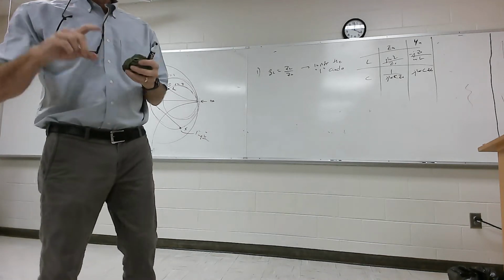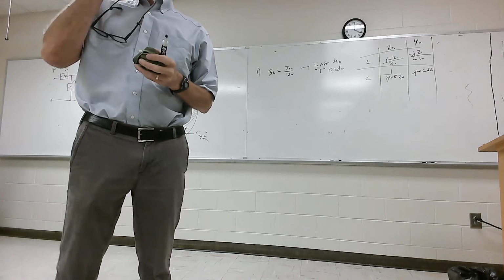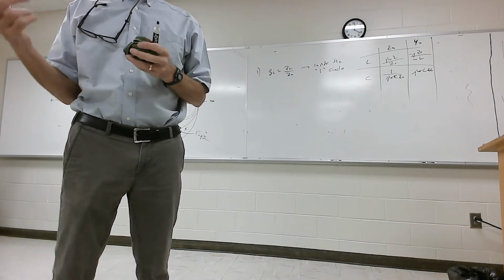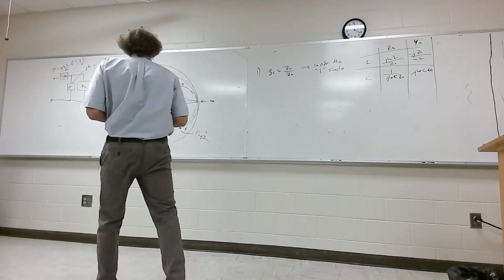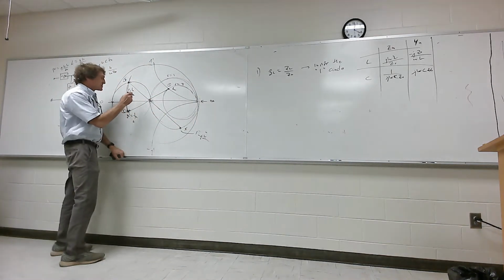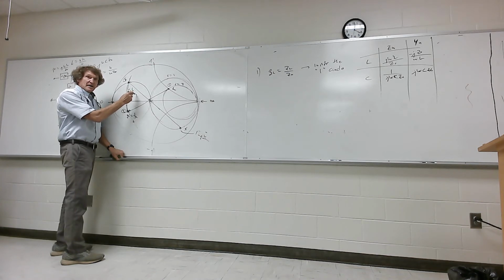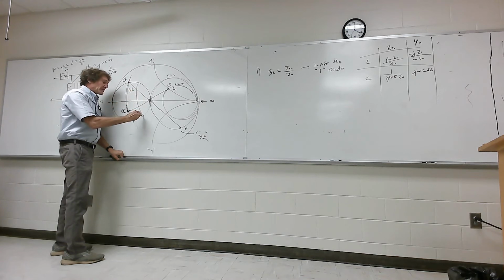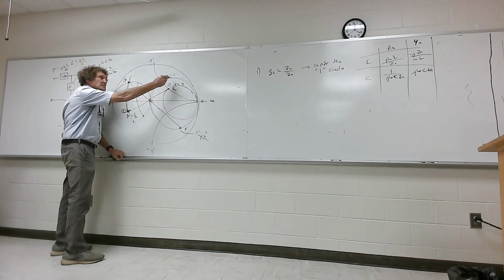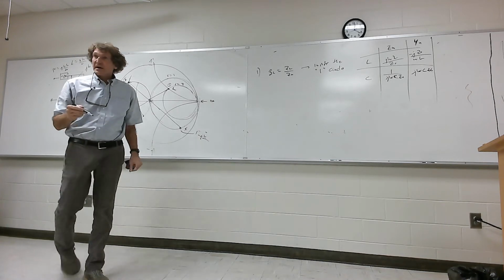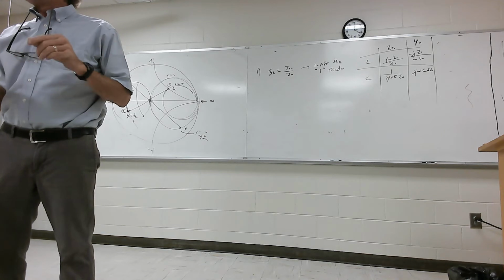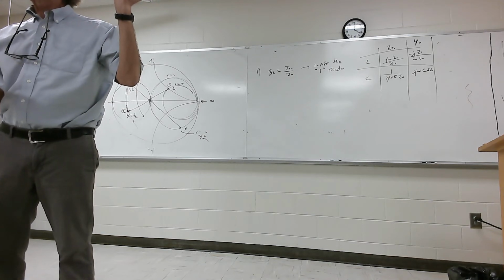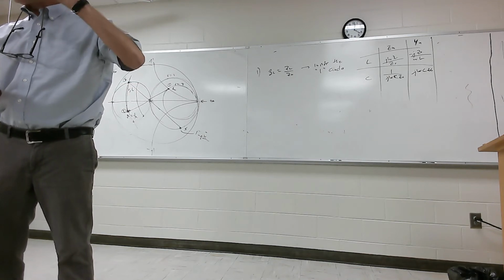Before I do one, I want to mention that's if you're inside the 1 circle. It means adding any series element, you can't get to that rim of 1. But what if we're inside the rotated circle? A rotated circle. This is an impedance. Now think about that. Here, we can add a series impedance and get to this rim. And the minute I'm at that rim, I can go to the admittance domain, and I'm on the other rim, and then I can add admittance to get to the series point, to get right to the center. Which means the first element would be in series. The second element would be in parallel.